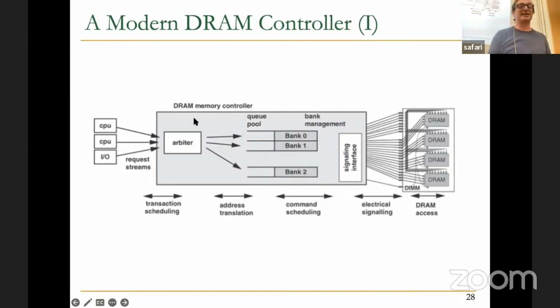Okay, so on the other end, the memory controller interacts with agents. Essentially, this could be CPUs, GPUs, FPGAs, I/O engines, the direct memory access engines. Essentially, a lot of different things can be connected to the memory controller over here. And today, many things are connected, as we will see soon. And these all basically keep injecting requests to the memory controller. The memory controller's task is to actually get those requests, buffer them, and identify where they should go, which rank, which bank, potentially which bank group, depending on essentially the structure of the DRAM. So basically, which row, which column, etc. The memory controller really needs to do that translation. And once that translation is done, there's some queuing. After some point, there needs to be some scheduling mechanism that happens over here, right?